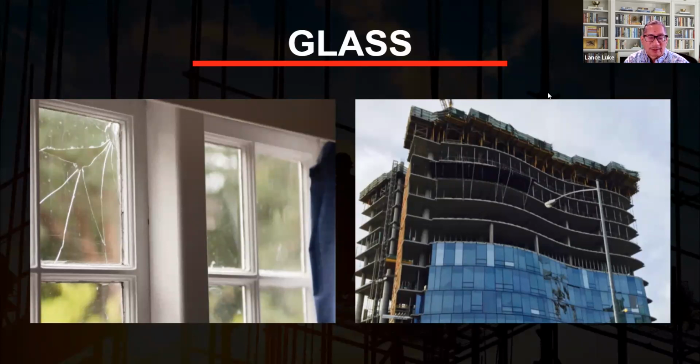And normally it's a thermal thing. When the window's facing west and it gets a lot of heat during the afternoon, that's when there's expansion of the window frame and the glass. And of course, when building material contracts and expands, it tends to move, and then the vibration. The glass is rigid, right? It's not like putty where it can move.